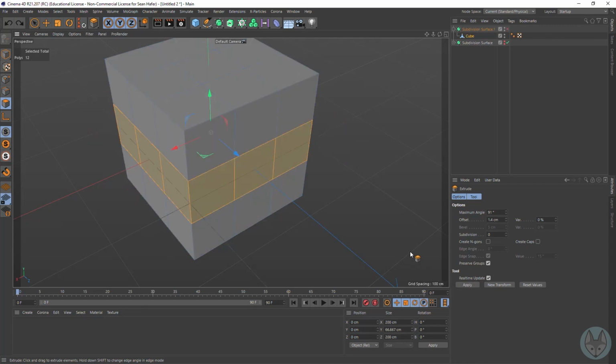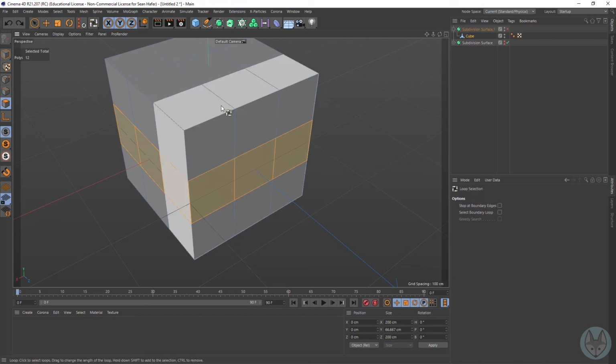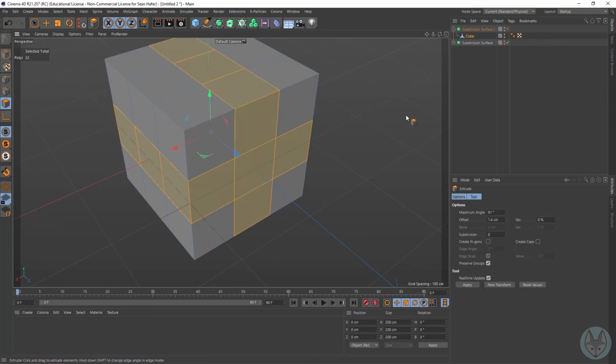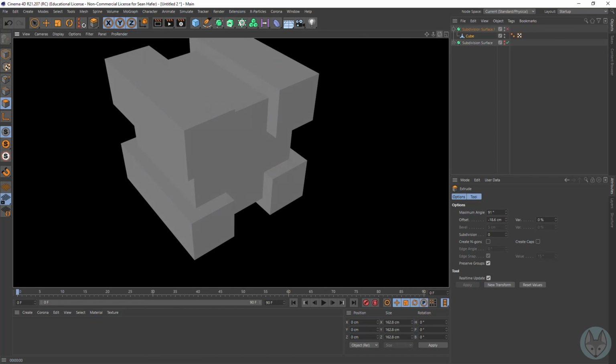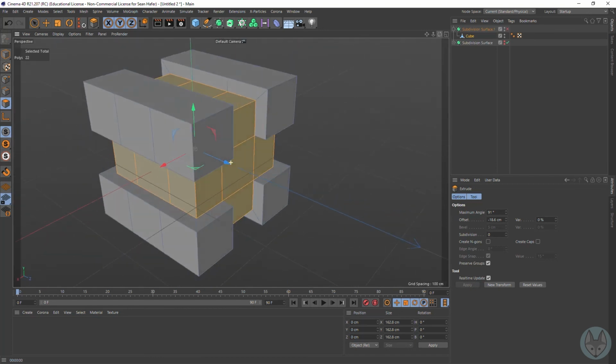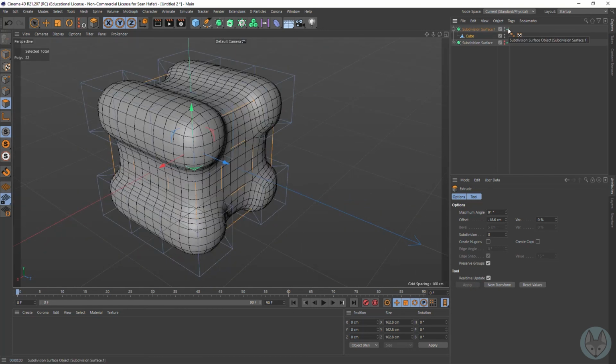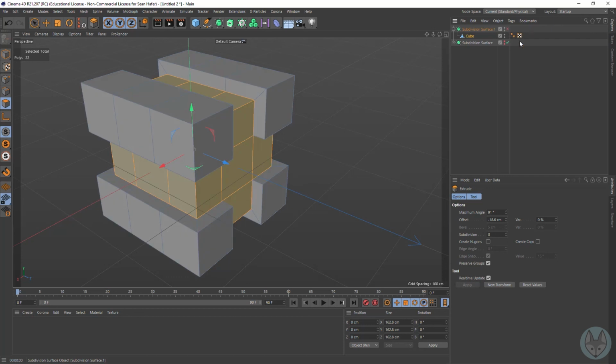So that's something that can happen there. I'll just undo a few times to get back in. So if I did that loop selection, held down Shift, UL for loop, I could grab both, right? And then maybe D, then just extrude to the left, right? And so now I've got this interesting shape that way. And if we came in, we could start smoothing that.